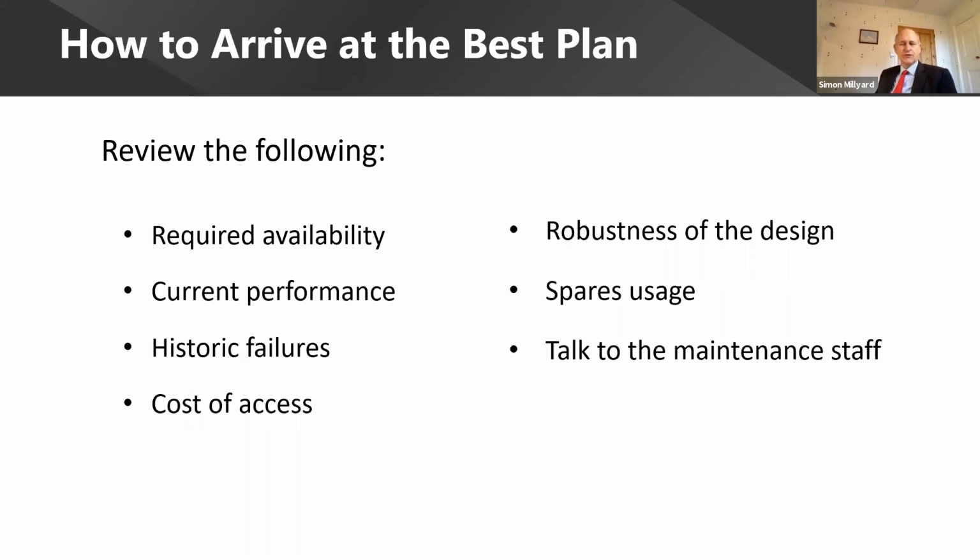Look at your spares usage, because that can be quite telling. Are you using up lots of one particular item, and if so, why? But above all, I would say, talk to your maintenance staff. That, in my experience, has been the most valuable source of information.